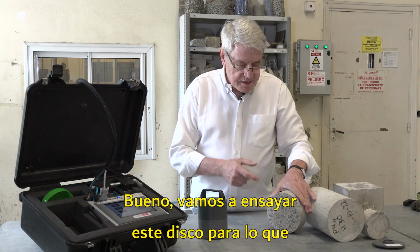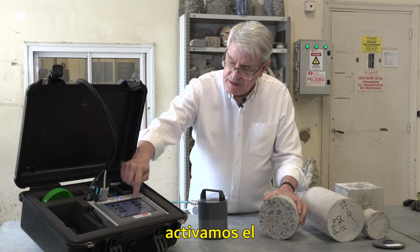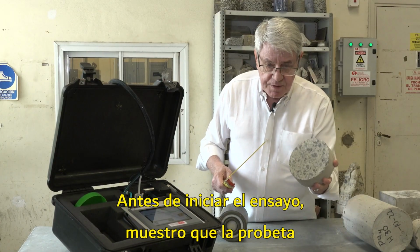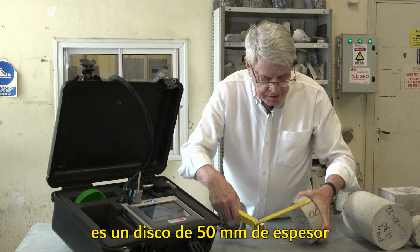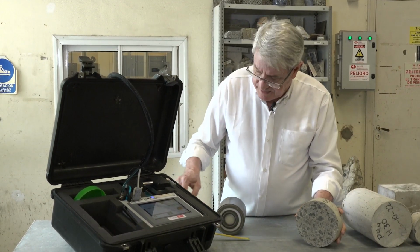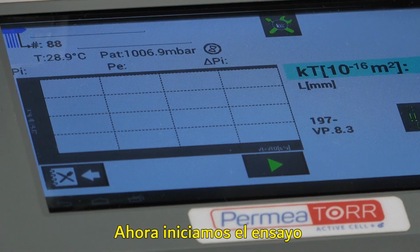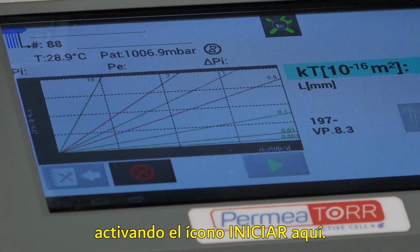Well, now we are going to run a test on this disc, and we press the icon corresponding to the test. Before we do the test, I show the specimen. It's a disc of a thickness of 50 millimeters and 150 millimeters diameter. The moisture of this sample is around 2%. So now we can run the test, for which we press the start button here.